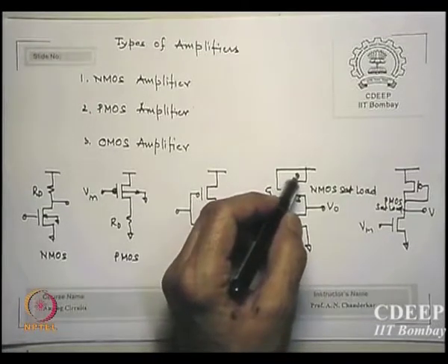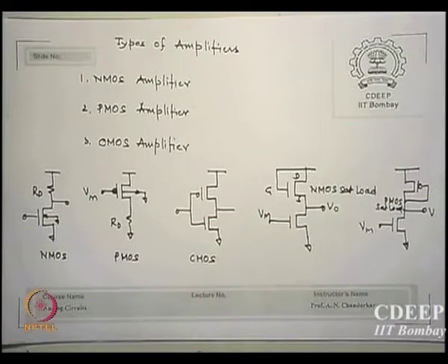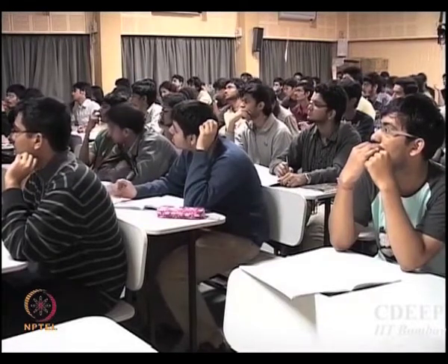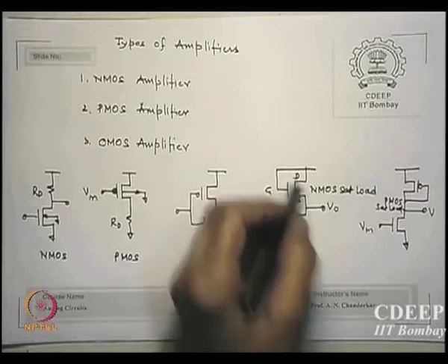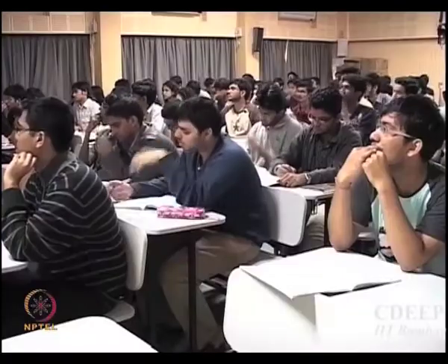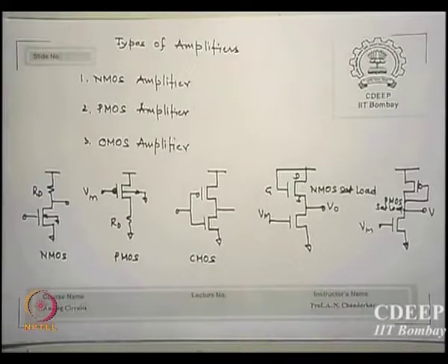So why did I call this the drain and not the source? Why was this upper lead not called source? Because they are identical, I could call this drain and this source, but I did not. In an N channel device, which carriers make transport? Electrons. Since electrons come from source to drain, the actual current flows from positive terminal to negative. Since the actual current is going down, the electron current is going up, that means the source should be lower than the upper side, because otherwise electrons can't move up. That is why they were given such names.